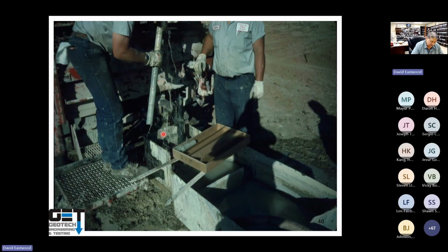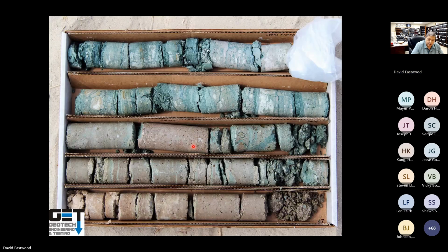Rock in Houston is about 2,500 feet deep. But if you go to San Antonio, Dallas, and Austin, especially San Antonio and Austin, you're going to see some rock sticking out of the ground. So if you put a street on top of it, that's great because you've got a great subgrade. The stuff I'm talking about today is on soil, clays, sands, and silts, which are a lot weaker than rock. So a 6-inch concrete paving on rock will perform much better than a 6-inch concrete paving on soil. So a lot of the stuff that I'm talking about is applicable everywhere in Texas.